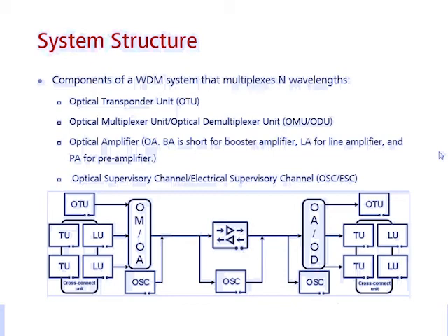But as for the customer service, the wavelengths are not standard. So when the WDM network accesses this kind of service, we cannot mix them into the same fiber directly. So before we mix them into the same fiber, we should make all the services carried by standard wavelengths. So which unit can help us do it?